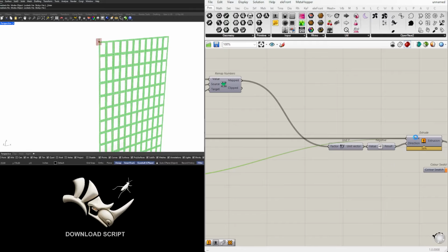Now we need to be careful because notice that I plugged it in from the output into the base input. This is going to cause issues because that's going to be a grafted set. So it's going to double the work that it needs to do. And you need to make sure that you flatten the input so you don't get this issue. So let's let it recuperate here, and then I'll show you how to avoid this issue.